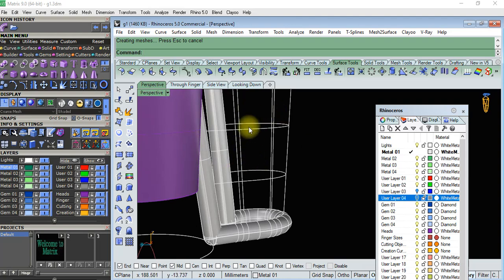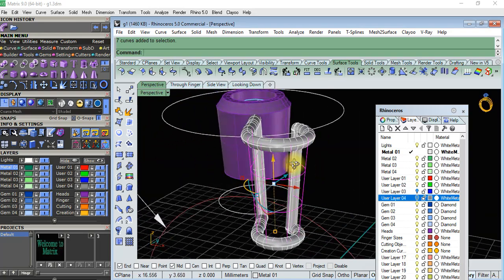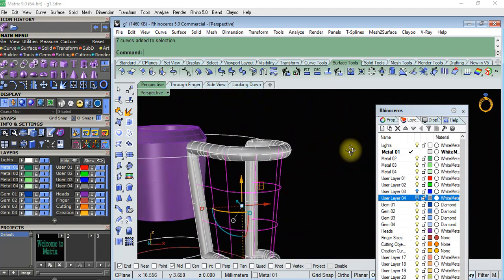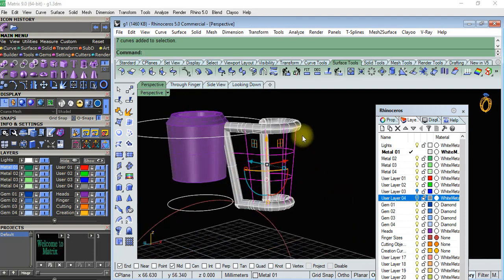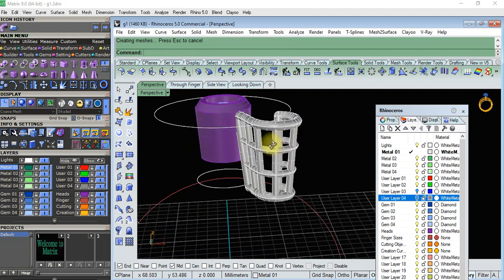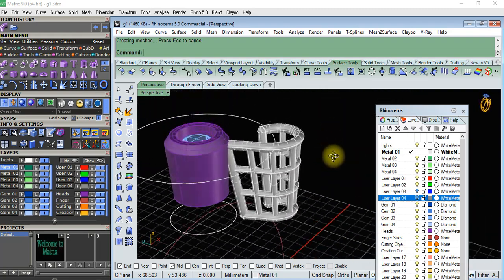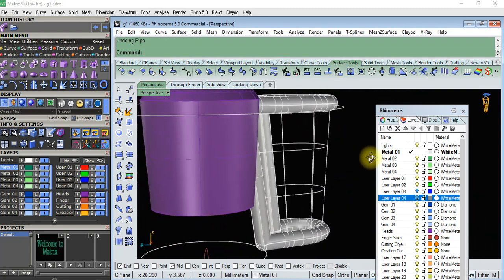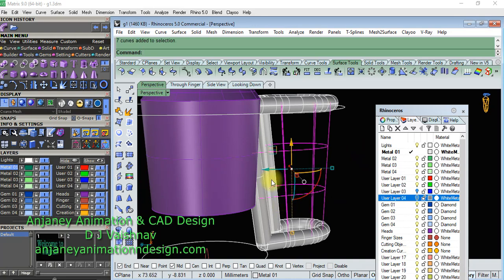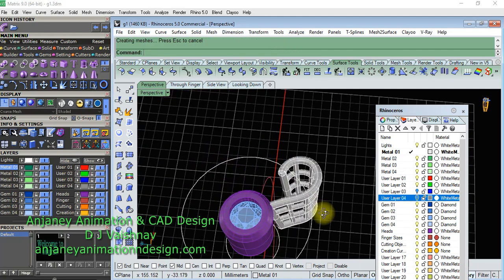And for the inner ISO curves, select them. Use the proper direction, orient your view to select the curves, and again use the same option, round, and we will just change the radius. Okay, this is fine, it looks great. We can also change it to 0.2. So select them, right click, round, and 0.2. Okay, so this is fine.